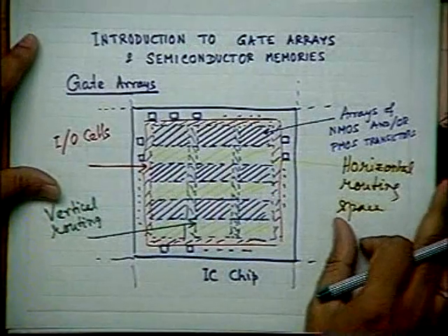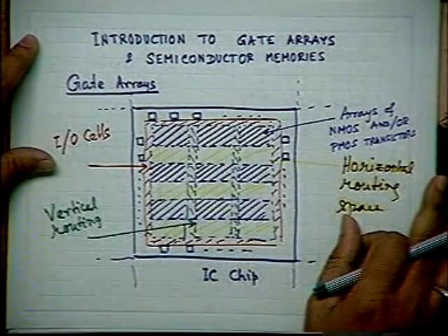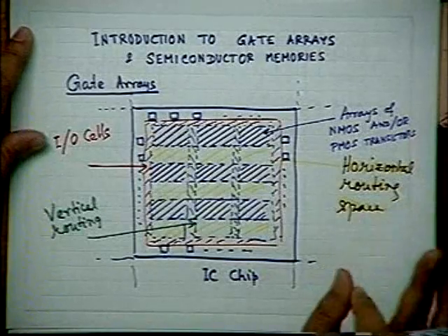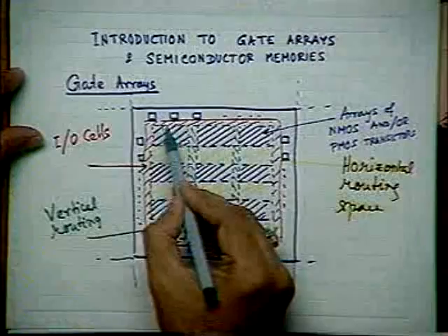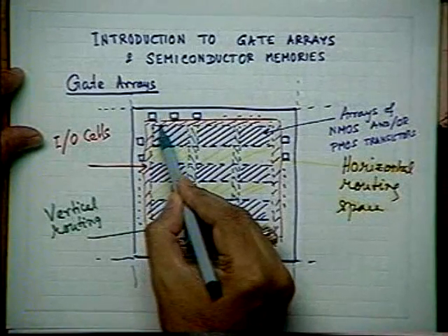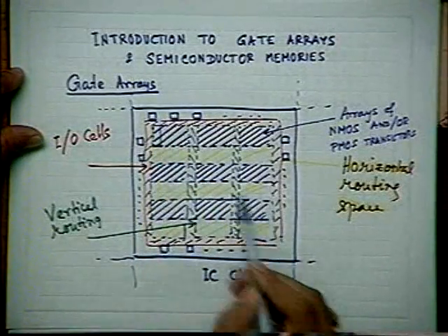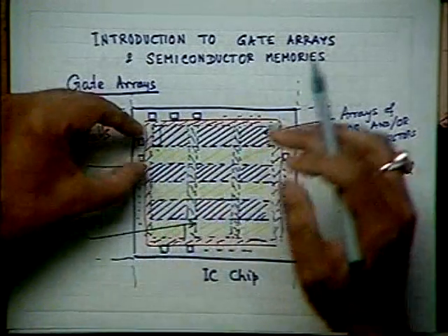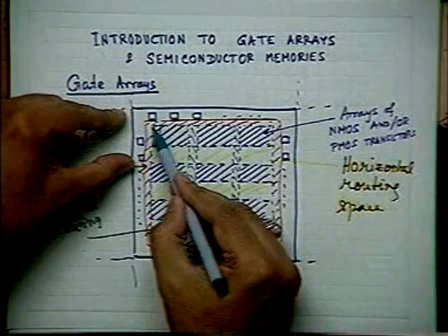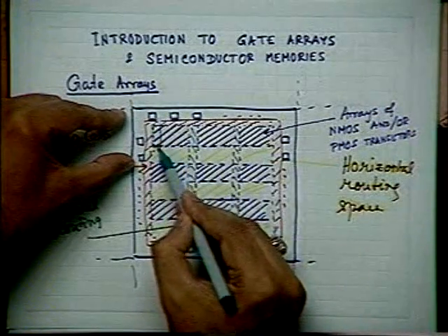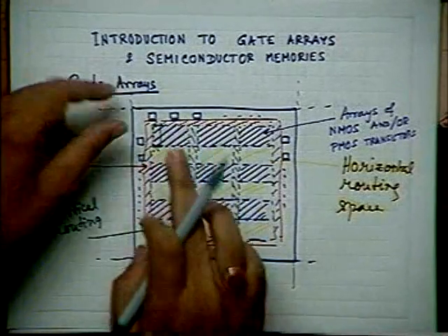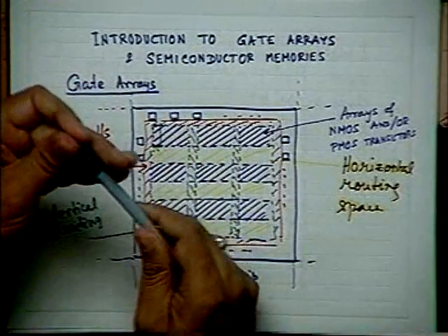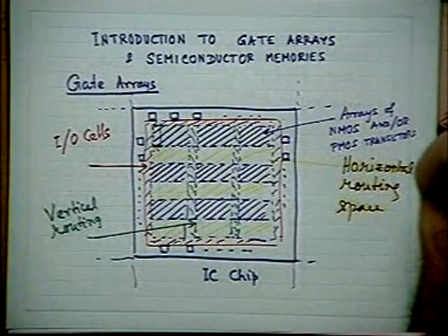Suppose a digital VLSI consists of 5 exclusive OR gates, 3 ALUs, 6 flip-flops, that kind of thing. So maybe I will place one exclusive OR here, but you see that this vertical size has been kept the same everywhere. And this is the region where I will put it. But these are the regions where the pins are available. This is what in the language of VLSI CAD is called placement.